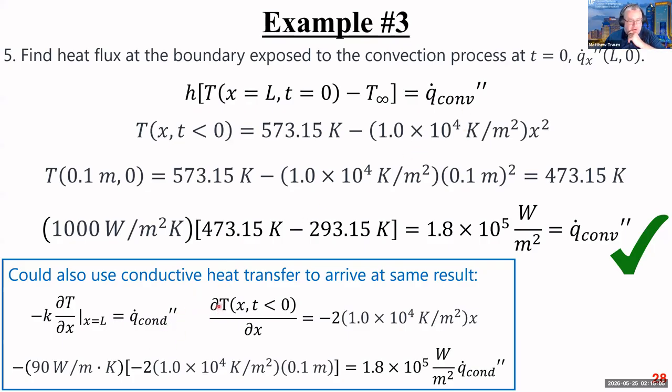Okay, so here's that first derivative of temperature with respect to x, which I calculated before when I was going through my derivative. So there it is. And now I just have to plug in my known k value, which is this. And I have to plug in this equation, which is dT/dx, for a given value of x, which is 0.1.